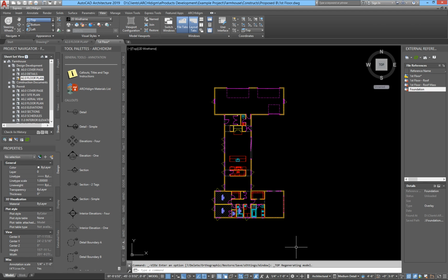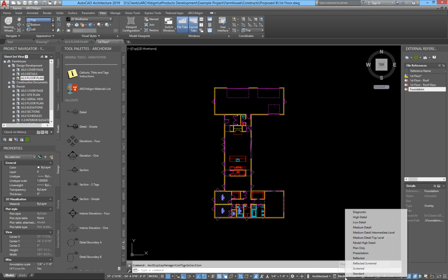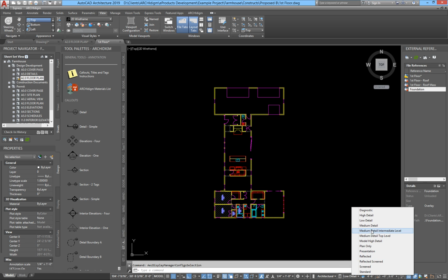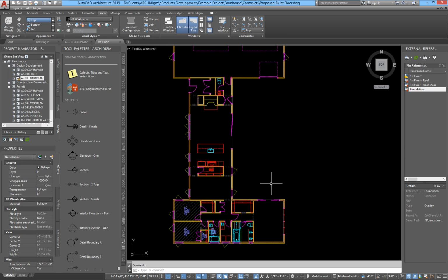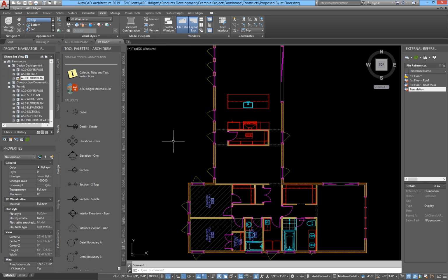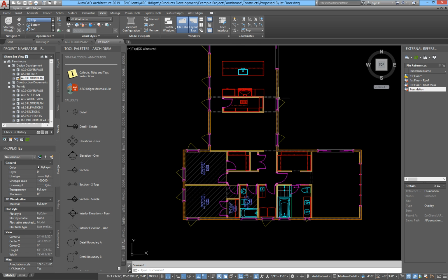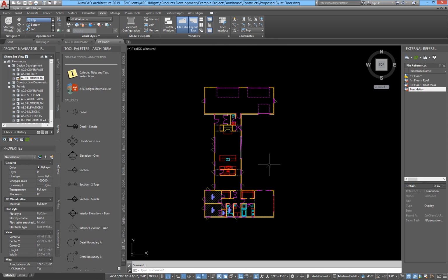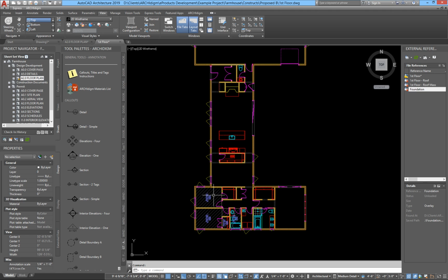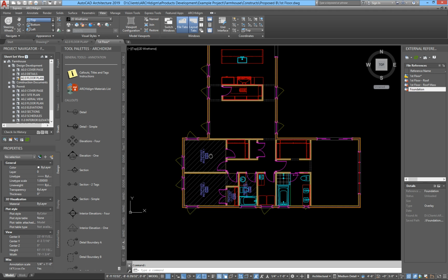The first thing I would do is make sure I have the display configuration set up to the one that I want to convert. For example, I might want to do Low instead of using Medium, but I'll use Medium here. And I may want to freeze things out that I don't want to convert, or I may delete them. When I do this kind of work, I never save the file itself, because I typically will do things to the construct file that I don't want back in my project. These are things that I do to make the conversion more successful or improve it.